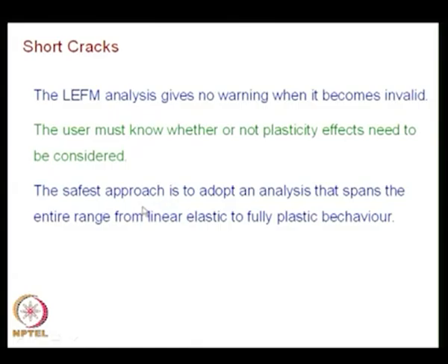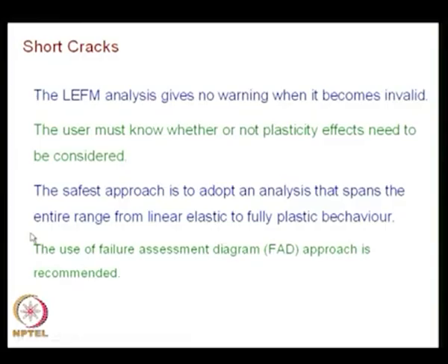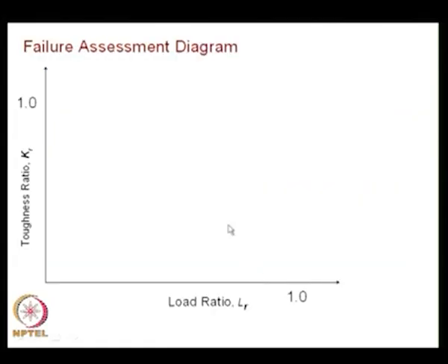The safest approach is to adopt an analysis that spans the entire range from linear elastic to fully plastic behavior. So, keeping this issue in mind, I have discussed the rudiments of the failure assessment diagram, and that is also summarized here. To take care of the issues that you have raised, the use of the failure assessment diagram is recommended, and we will also see how this diagram originated.